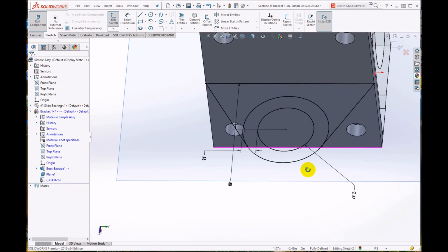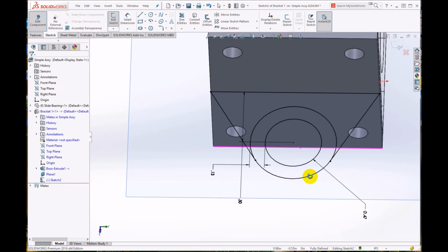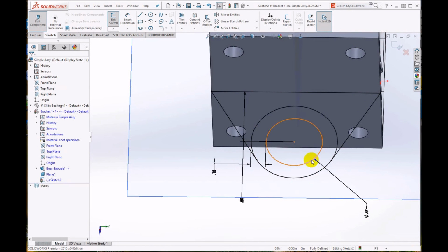Before I'm almost ready to extrude this feature up and down, you'll see a thing called midplane in a moment, but I have this line here. See, this is a complete circle, and I really don't want a complete circle. What I want is this area plus this area extruded. You may find that you don't have to do the following step. I find it's just cleaner and more obvious from a design intent.